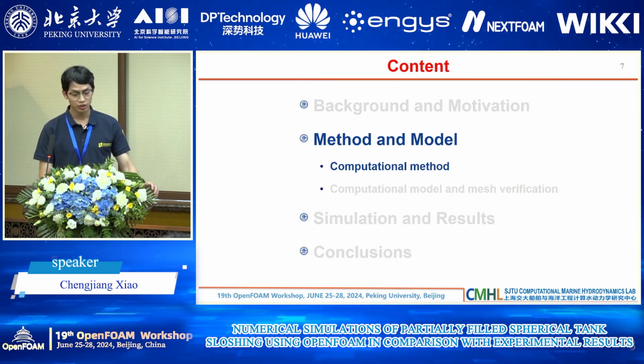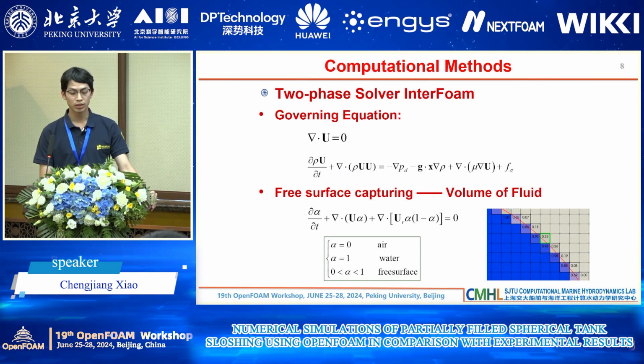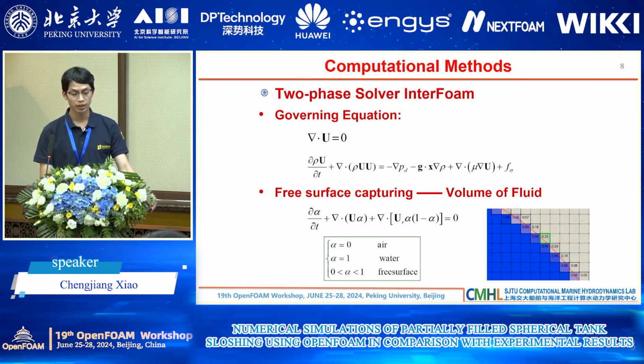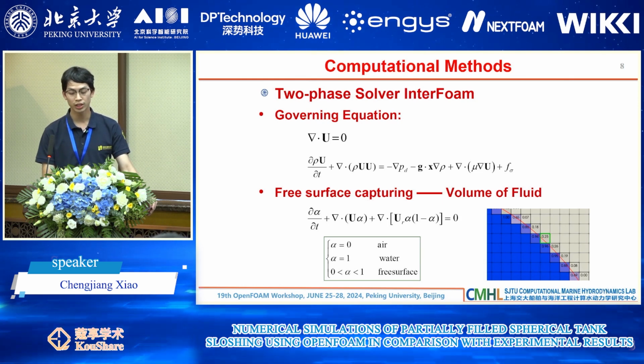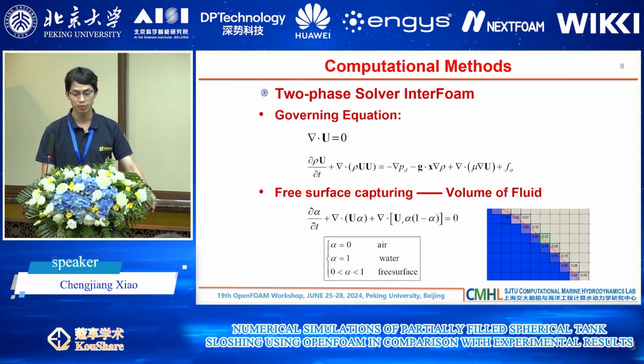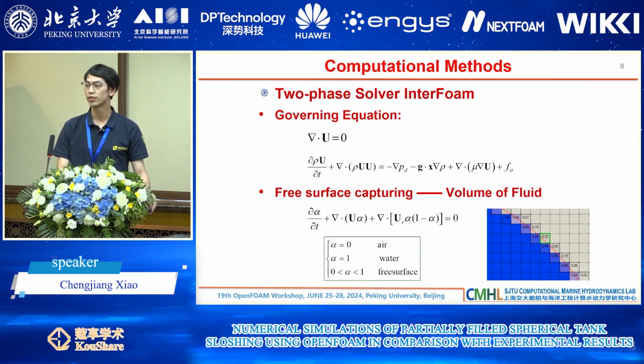Now let me introduce the simulation method. In our work, a CFD technique with the Euler method is taken into account. The built-in solver interFoam offers detailed visualizations and precise control over boundary conditions, performs well at free surface flow, and captures fluids'